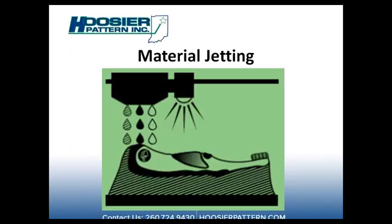Material jetting is where droplets of material are deposited layer by layer to make a part. The common varieties of material jetting include photo-curable resin and molten material that solidifies at ambient temperature. So these materials can be photopolymers, polymers, and waxes.